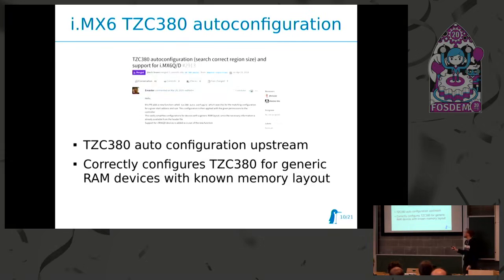It's also important to remember that there may be some kind of bypass for this TrustZone controller. For IMX6 platforms, as an example, there's a single bit in the IOMUX which you need to set to disable the bypass of the TrustZone controller, because you have certain bandwidth, so there's a small reduction of bandwidth going through the DDR firewall. And you have to disable this, obviously, because otherwise you can just bypass the firewall and everybody can read your secure world memory, which is rather bad.